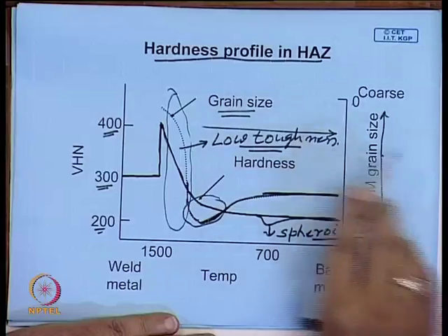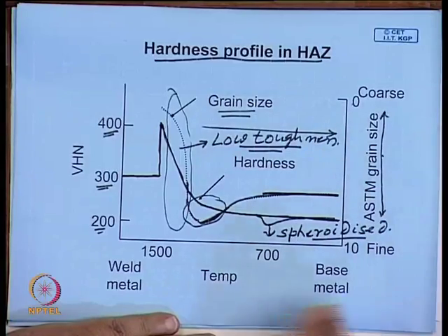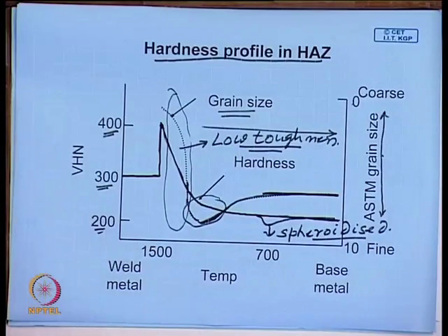During the welding process, if you are not able to protect the weld metal from the surrounding gases, then these gases can get dissolved, and particularly among these gases hydrogen is quite damaging, and hydrogen diffusivity is quite high.